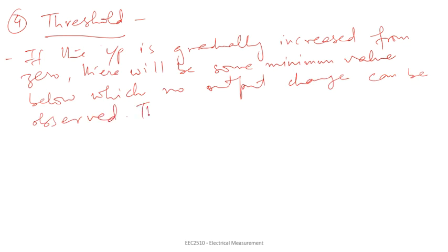This is known as threshold. So there is a difference between resolution and threshold. Resolution defines the smallest measurable input change, while the threshold defines the smallest measurable input.